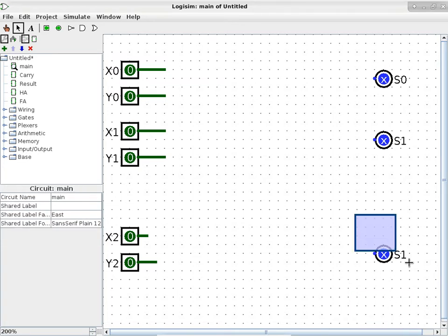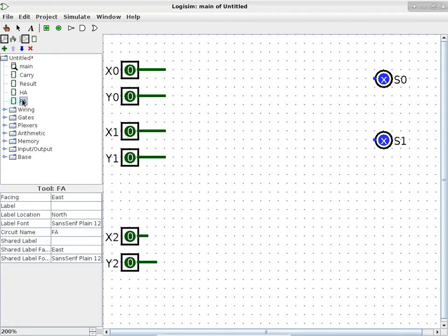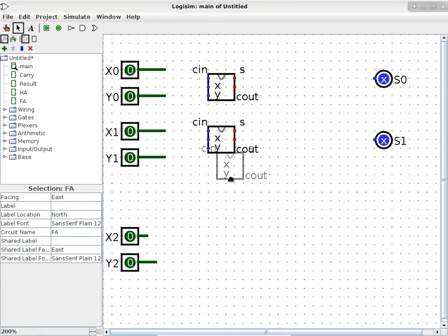So, yeah, it's unpleasant. All right, so now that we have full adders, let's slap some full adders on here. One full adder per column. So we have one here, one here. Okay, let's just stick with a 3-bit adder because the 4-bit adder is going to be pretty much the same thing except it's just one more bit.